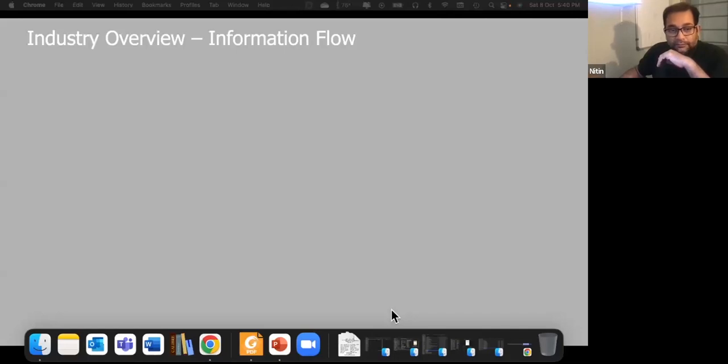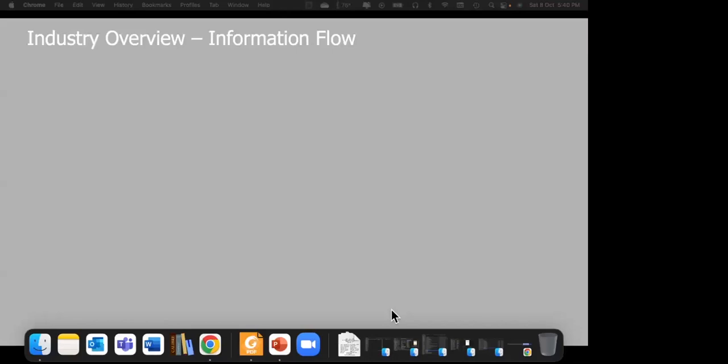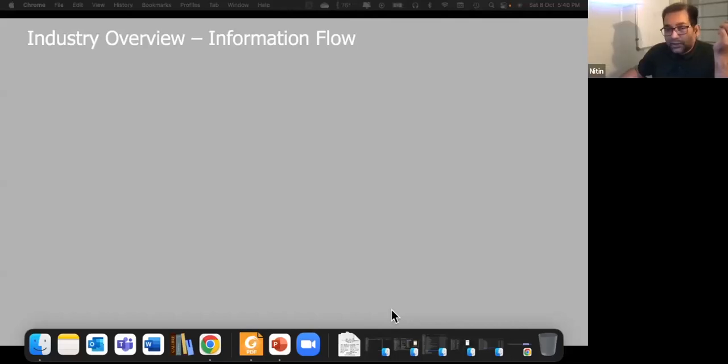Okay. Then we go much higher. You can say this is SCADA, HMI, and monitoring and supervisory control. In process industry, we call it APC control or RTO control. APC is advanced process control, and RTO is real-time optimization. And then ultimately it goes to the manufacturing execution system and ERP. One of the things you are seeing is the change in the time frequency. The data is constantly changing, and the flow stops here. After this layer, these layers are not directly connected to the production system. It is more about what we are seeing, how much we are seeing, and how we guide the systems below to make changes. So this is what the degradation changes are.